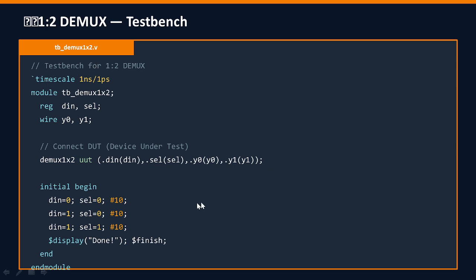Inside that, you are going to map the inputs, outputs, and select lines. What is this called? Mapping formatting. You can write d in, comma, select, comma, y0, comma, y1 like that also, but sometimes it is going to create an error. To avoid that error, you need to use a formatting structure, which is called map formatting.